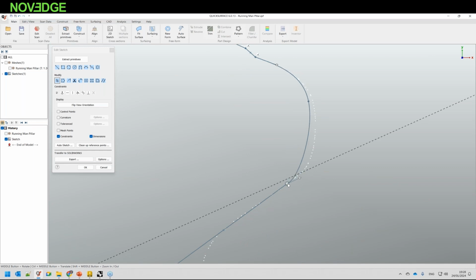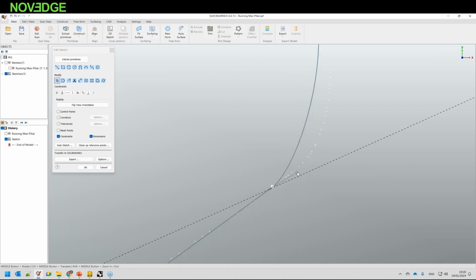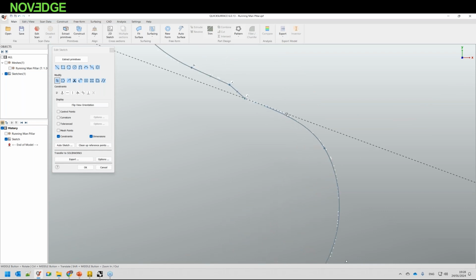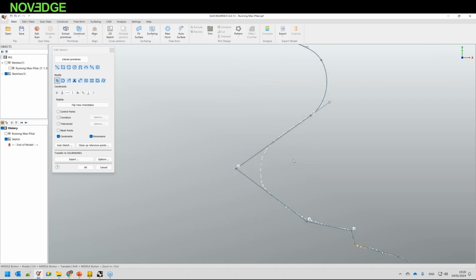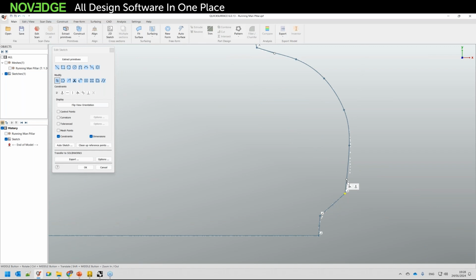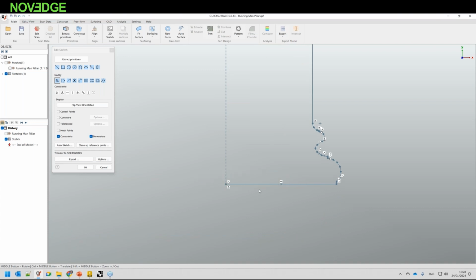I can just connect the shapes here. Of course, because this is a spline, I can always do the tangency using the control points. I can change the curvature so I can get as close as possible to the desired result. You can see this is a classic approach. Again, with the Control, this will be defined as a fillet. And let me just finish this profile here, and perhaps I'll just leave it as it is on this shape. Holding the Control will intersect.